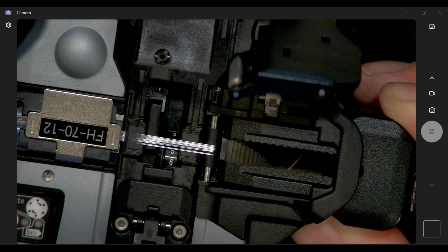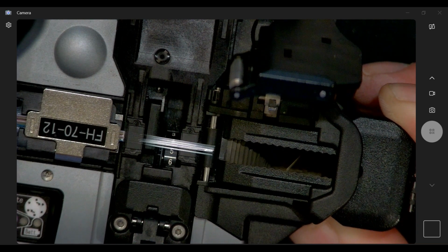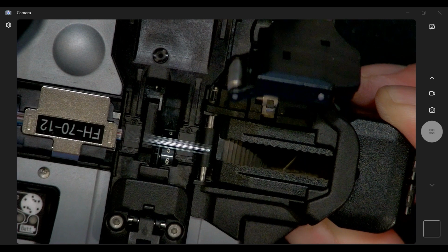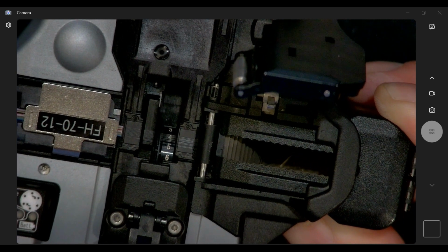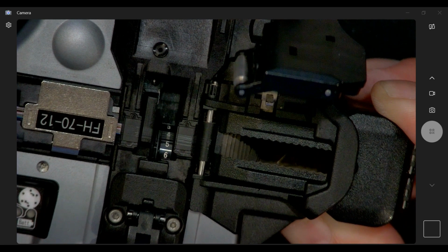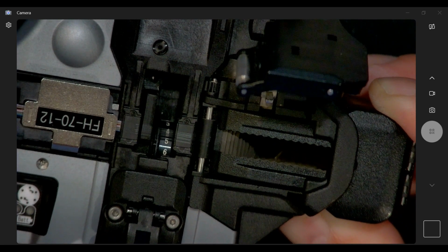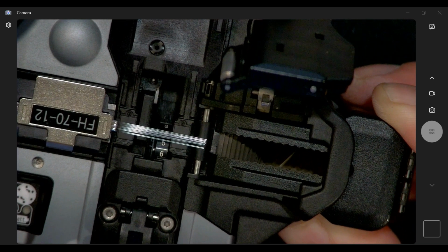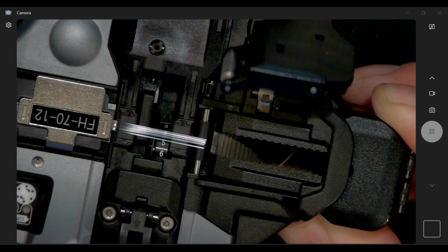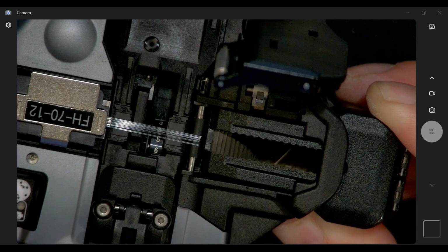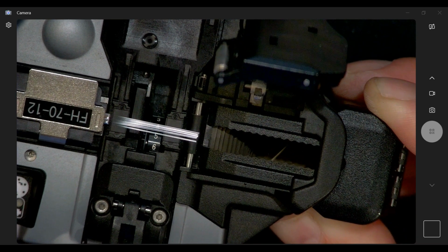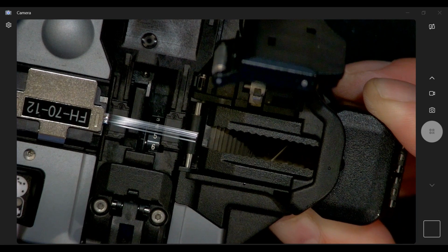If you get a poor quality cleave, it's really not the calibration of the cleaver causing the problem. It's where the fibers in here are slightly imbalanced. I would not go and press this forward. Honestly, I would probably make a little bit of adjustment for it. And you'll notice here also that the fibers themselves are barely over the apex of the fiber collection system.